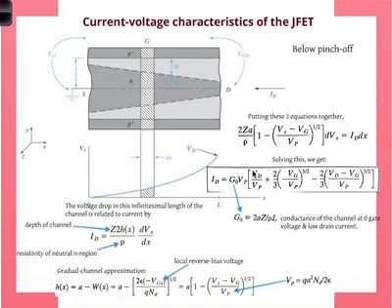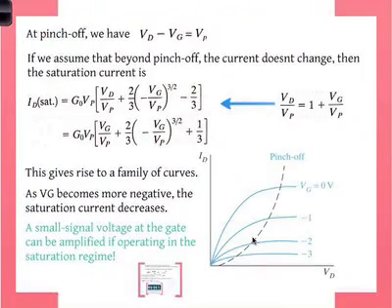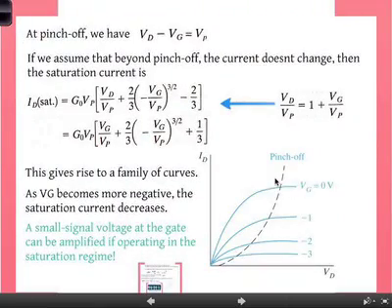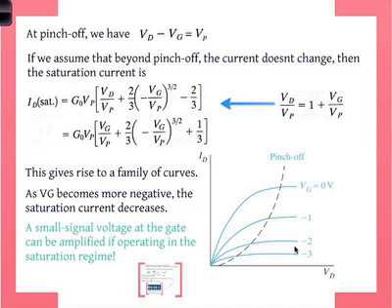Okay, so you have an input VD, and you have another input VG, and the output is ID, and everything else you can calculate. And that's how you get these curves. ID, VD, VG. Two unknowns, two inputs, one output. So your family of curves.